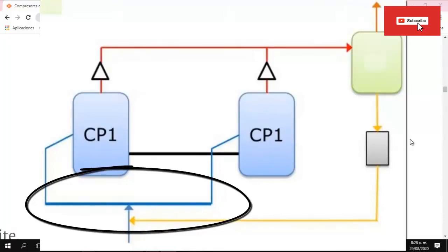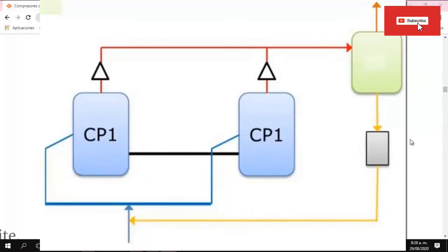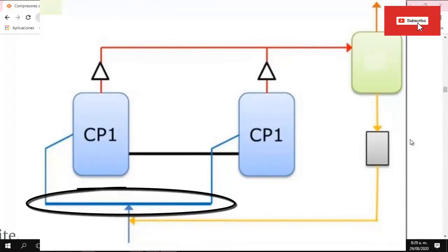4. To get a good oil level balance between two compressors, the oil return must be divided equally between the running compressors. 5. The state of the oil could be as dew or as drops along the length and curvature of the pipe. 6. Since the oil returns with the suction gas, equalizing the flow rate of the refrigerant is critical and the velocity of the gas in the suction line is very important. 7. The main riser line that goes from the evaporator to the compressors is connected to a riser head, where the pressures can be equalized.